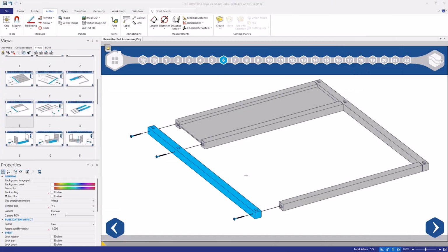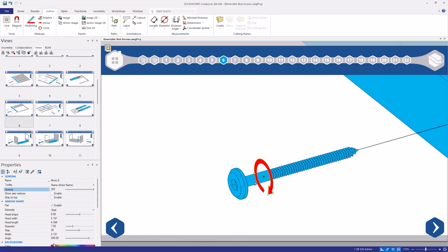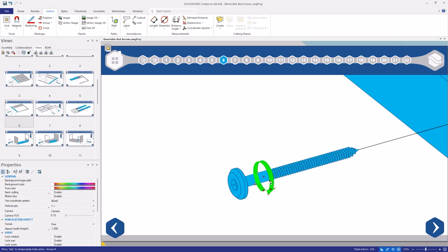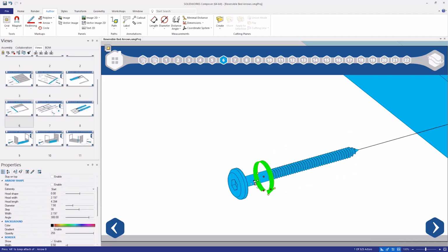The circular arrows are similar, but you don't need to hold Alt while finding the edges, as this is the first click you do, and the second is the length along that axis. A nice tool in the circular arrow is the flat option. Unticking this will turn your arrow into a more 3D arrow.